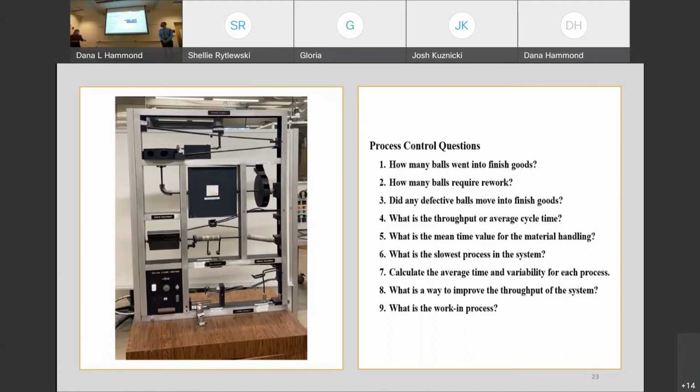and we came up with infrared sensors. We'll have 12 infrared sensors along the track that will indicate when the ball enters the system, enters or leaves a process, or leaves the system. The IR emitted LED light will flash red when the ball rolls by and triggers it. The reason we chose infrared sensors is because they're able to detect the ball within a certain narrow window and record the information. Also, they're small and lightweight.